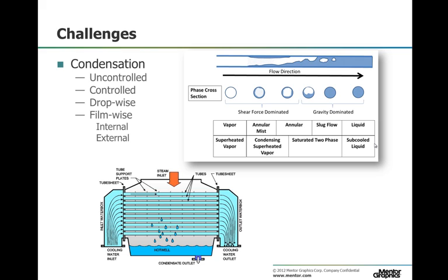Condensation is the cooling of the vapor until the phase change back to liquid occurs. Condensation can occur in two manners, controlled or uncontrolled. Controlled condensation is when components such as heat exchangers are added to the system with a distinct purpose of converting the vapor back into liquid. This is done for the purpose of reuse in closed cycle and also to stop uncontrolled condensation.